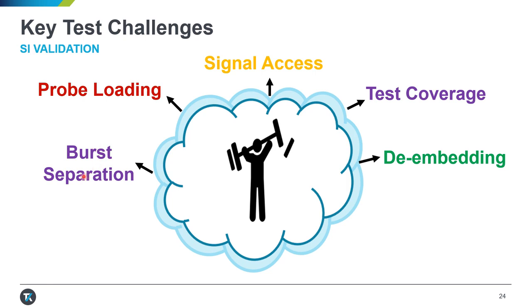Next challenge that we will face is bus separation. Now, this has been traditionally a pain point for all previous memory generations. Even in the good old days where writes were center aligned and reads were edge aligned, even in those days we had problems with memory bus separation. Well, there is no good news here. This will continue to be a problem even for LP5.